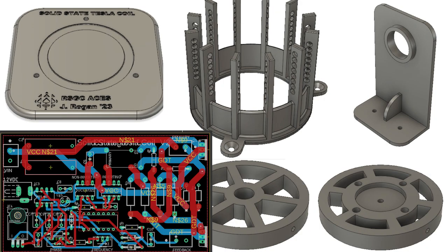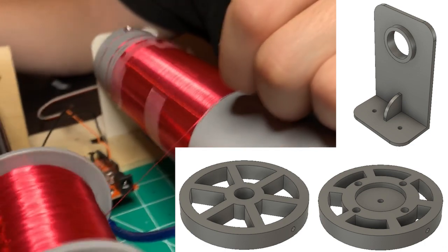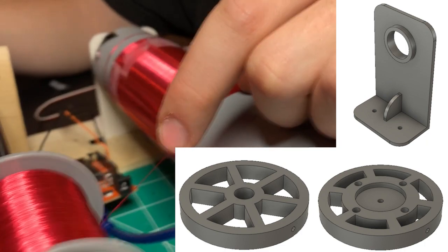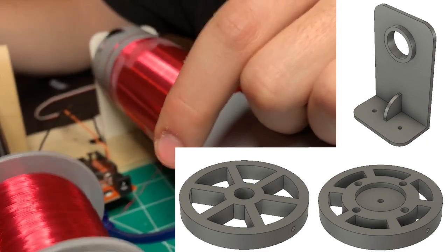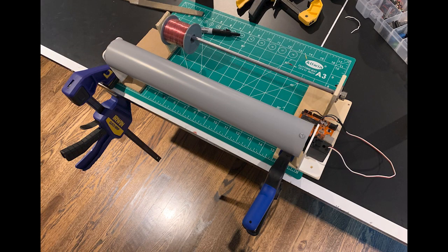So moving on quickly to design aspects, a couple of CAD tools and materials are implemented in different sections of the overall build. First of all, a secondary winding machine was made out of custom 3D printed parts, wood, and other miscellaneous parts. This winding machine made winding the secondary coil a lot easier than how it would have otherwise been, although it was still super tedious, and I would not want to do it again. The PVC form is mounted to a shaft via 3D printed support, custom designed in Fusion 360. The ends are taped off with electrical tape.